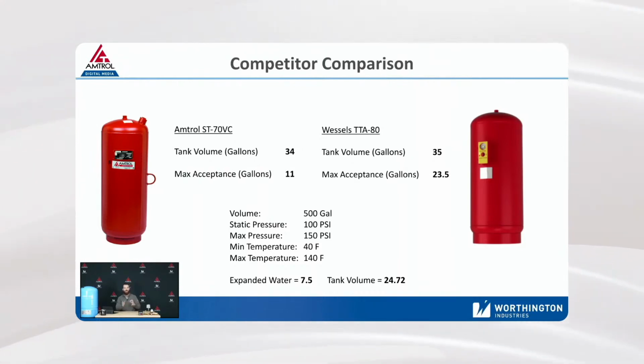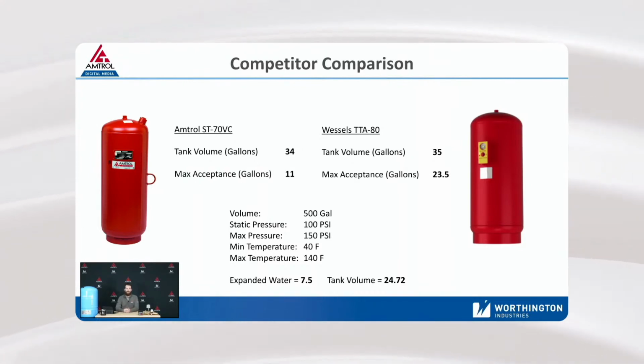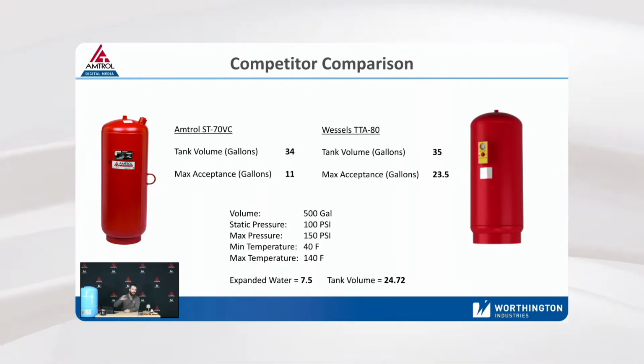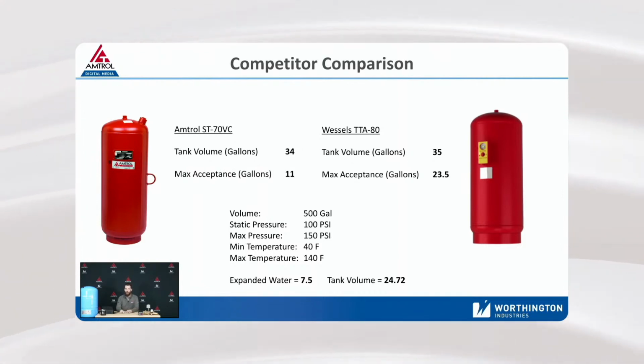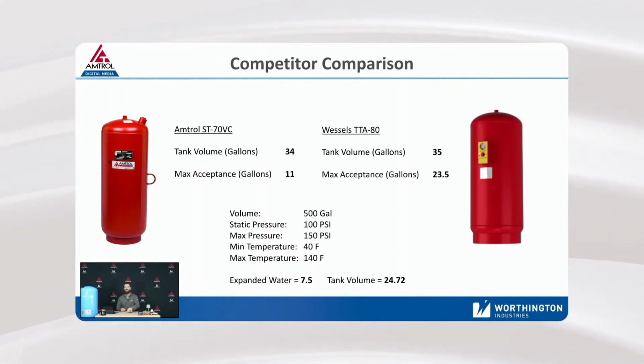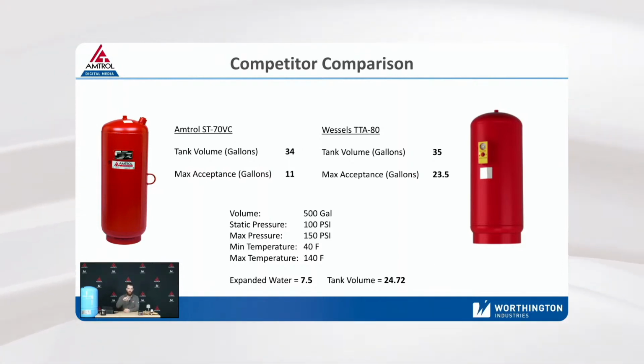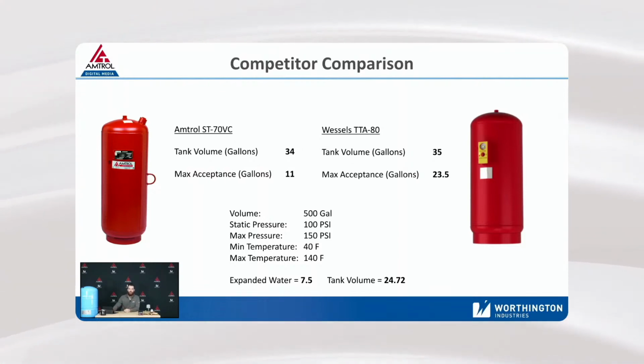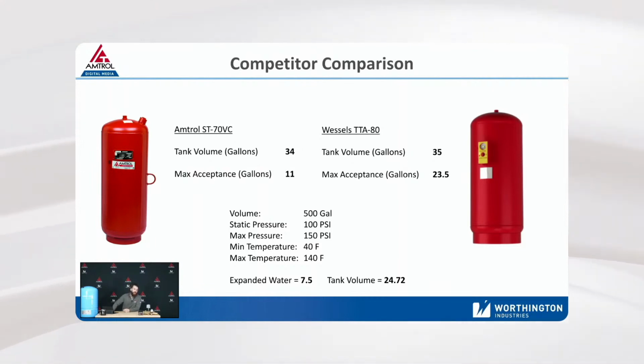It's kind of, you got to fight back and forth with that, of driving the focus on the system instead of the tanks. The tanks are victims of the system, if you will, or they perform only what the system is going to give them. They don't dictate their own values. Yeah, we can size them, but the volume going into them is given to them by the system. The tanks don't just magically create water. They're given water. So as long as we know how much water is going in, we can size these tanks confidently, and we can compete with these people no problem, because we know they're only going to use 7.5. So I don't care if the tank was full acceptance. It's irrelevant. It's all wasted space.